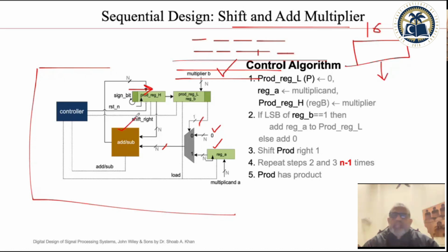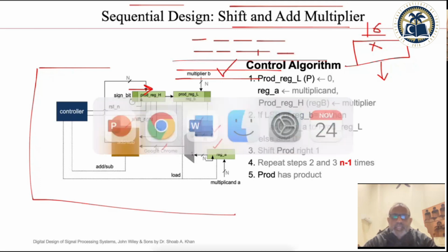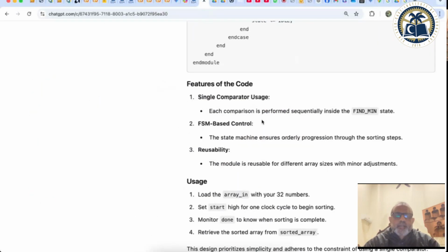You may say, okay, I'll use it, but sometimes you don't get into bit serial multiplications and additions. This is only a very rare case where you say, I have a lot of cycles and a lot of multiplications, so I don't mind putting even a single multiplier in my design. I convert it into fixed point, and then I have these types of multipliers, which are called sequential multipliers or shift and add multipliers. Let's see if it can generate.